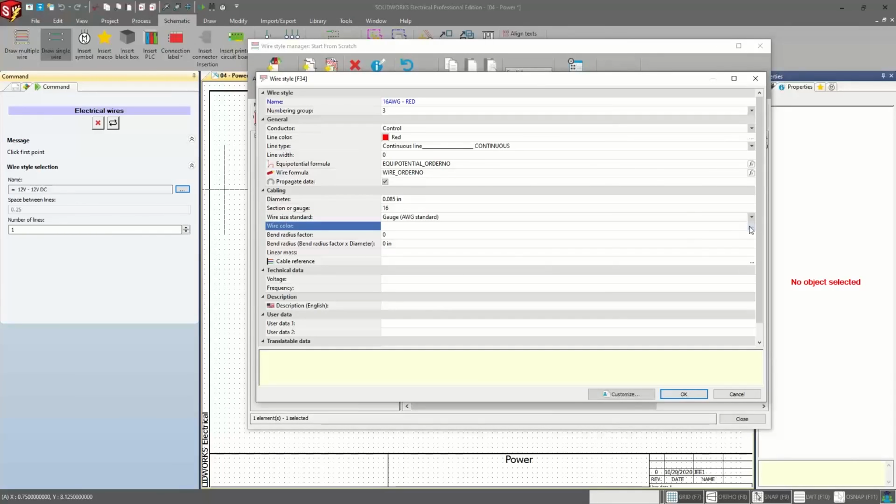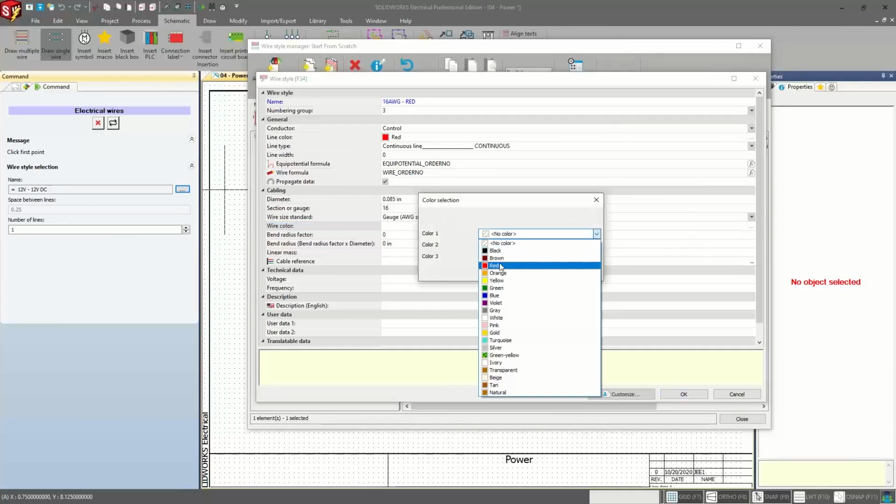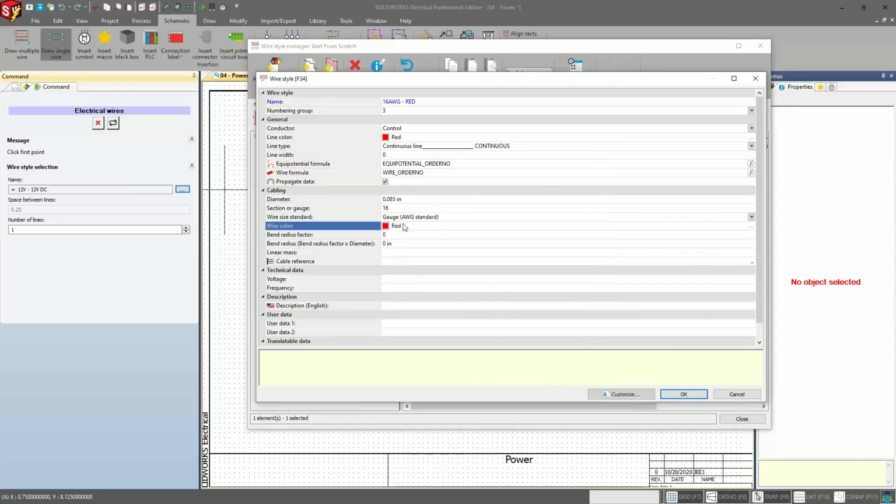And the wire color for that. So again, when I get to the 3D side, that's what this is going to appear as, a red wire. Now, if I'm dealing with something like fiber or a 14 gauge wire or even bigger, where the bend radius really starts to become a factor, RF lines, fiber, and large gauge wire, bend radius in general is something you might want to consider, because that will help you determine the appropriate bend in the 3D space.